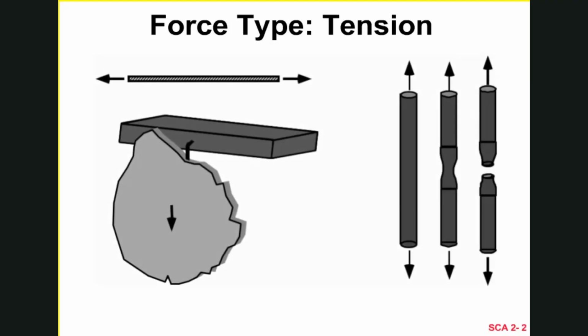At the rescue site, the things that we will see are like what is shown in the slide: a piece of concrete hanging from the structure, and an engineer that's knowledgeable would quickly know what the capacity of the reinforcing bars are that are hanging the piece, and could make some kind of a judgment about whether it's a good situation or a bad situation.